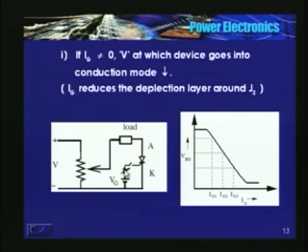And I am varying this resistor to vary the current flowing through the gate circuit. So as Ig increases, the voltage at VBO, with a very low value of Ig, is almost the same. This voltage is determined by junction J2 itself.